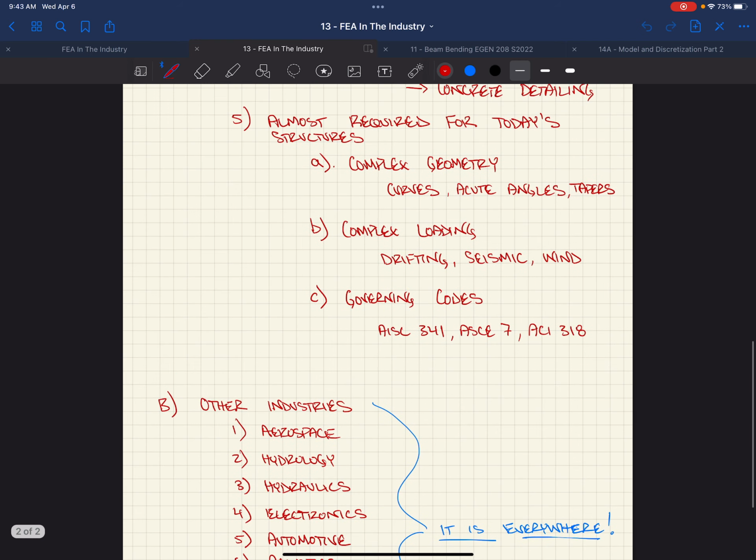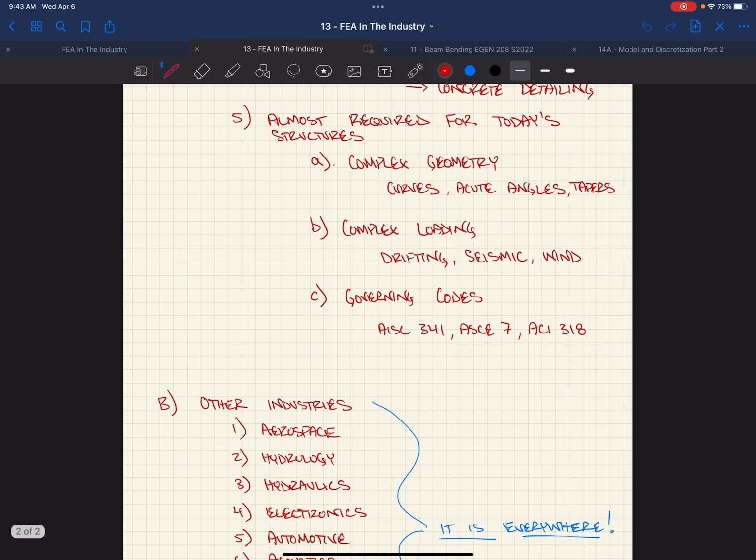So the governing codes kind of make it, right, in the teal book, the sizing manual, if Damon gets to it, when you load up brace frames, they give you an analysis, they give you a list. You gotta look at the capacity dependent loads, but also you gotta look at the resistance of the building to overturn, right? Could it just overturn? That would limit your ability to actually push on the system. Also, you can do nonlinear analysis of your buildings now. They let you do that as well.